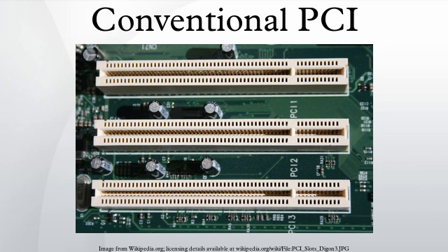Configuration access addresses for PCI Configuration Space access are decoded specially. For these, the low-order address lines specify the offset of the desired PCI configuration register, and the high-order address lines are ignored. Instead, an additional address signal, the IDSEL input, must be high before a device may assert devsel. Each slot connects a different high-order address line to the IDSEL pin, and is selected using one-hot encoding on the upper address lines.